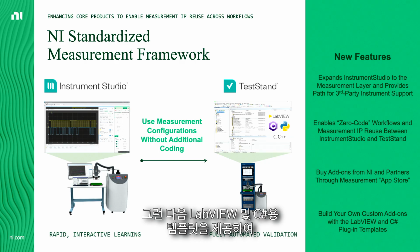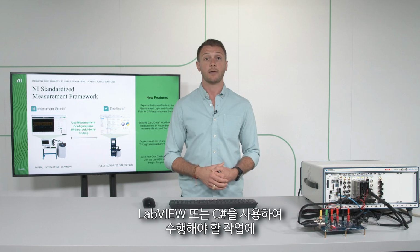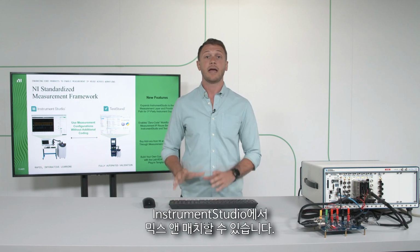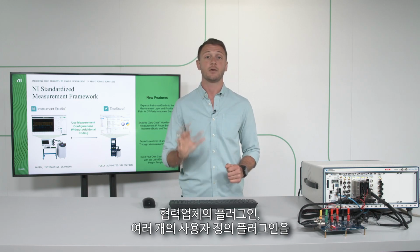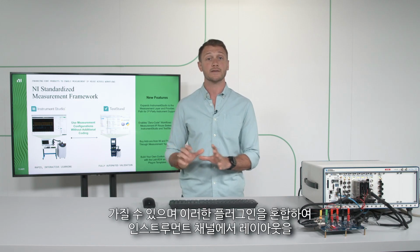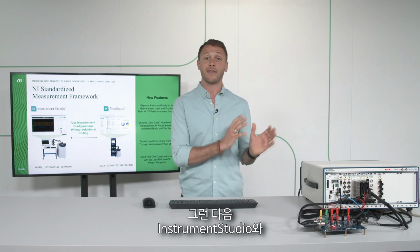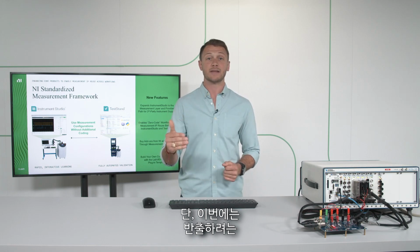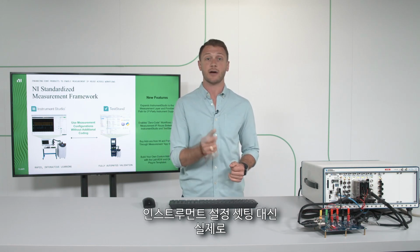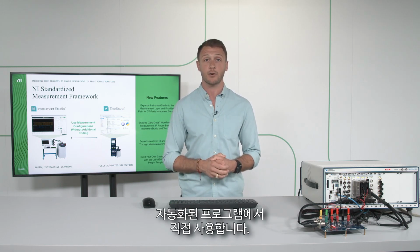Then we're going to provide a template for LabVIEW and C# so that you can develop your own add-ons to Instrument Studio. You can use LabVIEW or C#, create a plugin that is specific to the job that you need to do, and then you can mix and match those in Instrument Studio. So you can have maybe one or two plugins from NI, you can have a plugin from a partner, a couple custom plugins, and then mix those to create layouts with instrument channels as well, and then follow that same workflow between Instrument Studio and your automated programs. Except this time, instead of being instrument configuration settings that you're exporting, you can actually export measurement configuration settings and use those directly in your automated program.